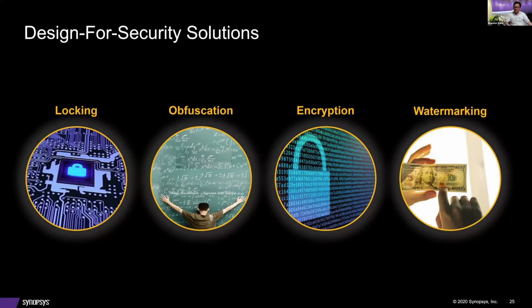So we look at the aspect of logic locking, which locks the circuit, enabled by a key, but does not necessarily hide the structure of the design. So people can see the structure. It might split the design to prevent the complete functionality until the key is provided. Now logic obfuscation will hide the structure of the circuit.